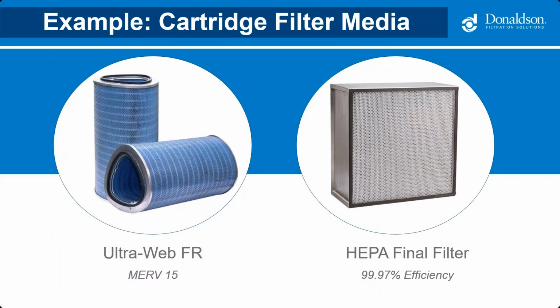So in terms of the filter media inside the cartridge collector, I would typically recommend a nanofiber filter. What this does is it allows for a dust cake to form on the surface of the filter, ultimately creating a higher efficiency media. I also recommend a flame retardant style media for laser cutting, just because of the sparks that are present in the laser cutting process and could be transported to the dust collector.